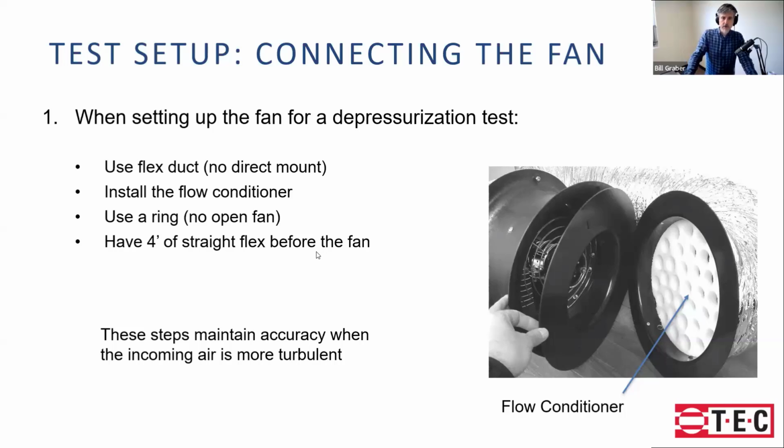Yeah. And I've heard people use depressurization. Maybe you're going to touch on this, but they prefer that because it pulls the tape or whatever you've put over the registers, kind of sucks them in as opposed to pushing against them. But you can see it's a little bit more problematic to do the setup of the fan itself.